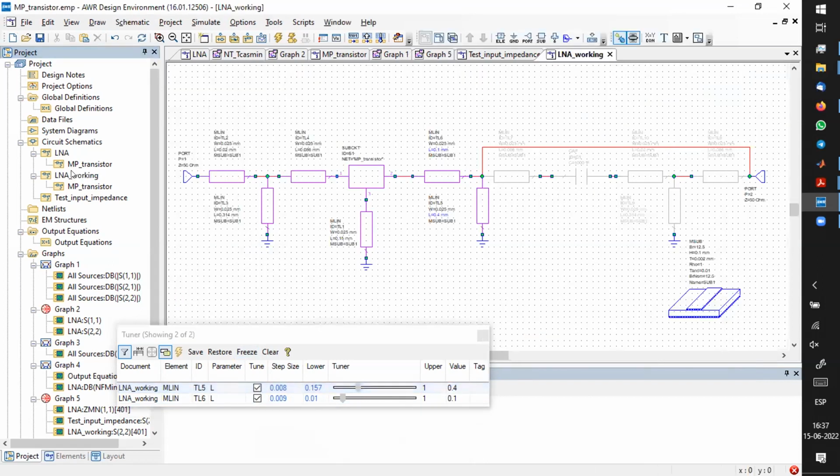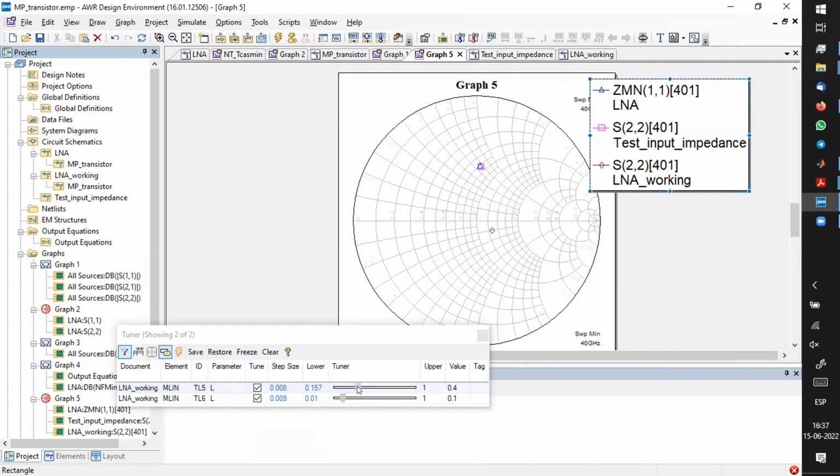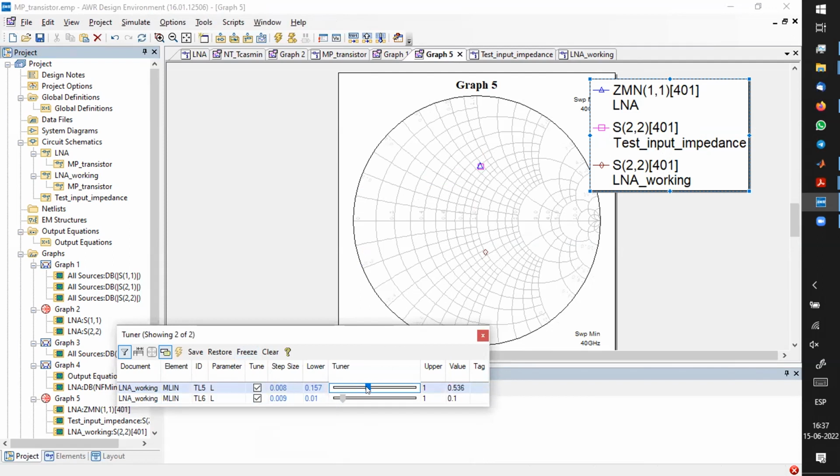You are now on the wrong side of the Smith chart for some reason. Keep that one as it was. But the series line, I think you changed the length, or did you? If you make it a little longer, like 200 or something, that's okay. Let's keep it there. It looks good.